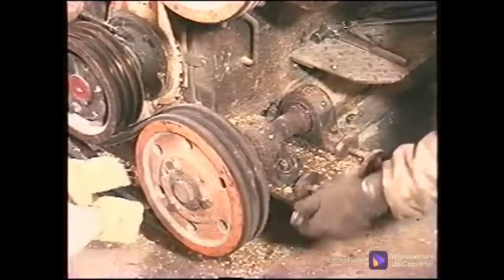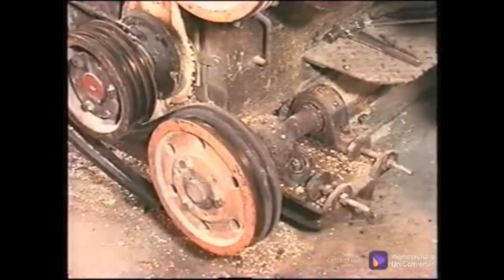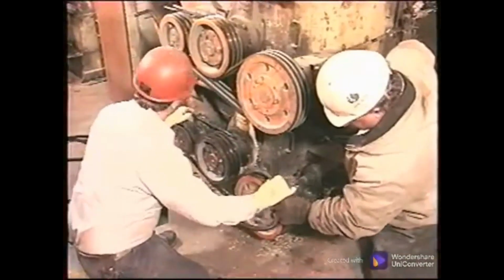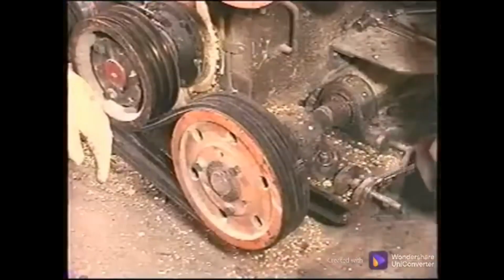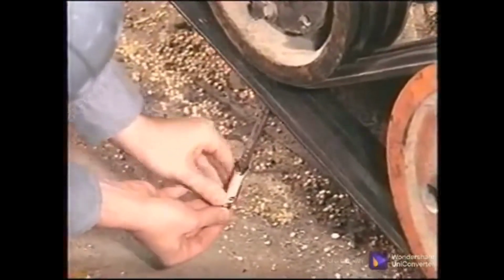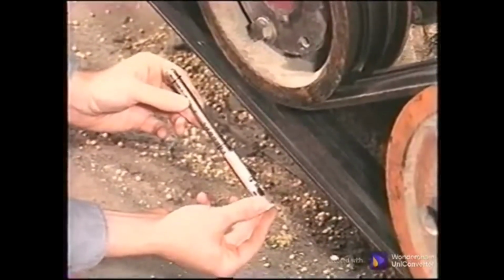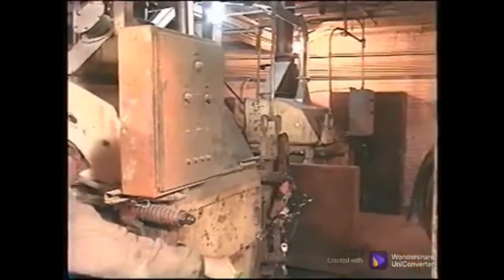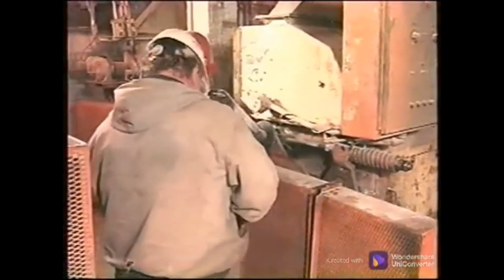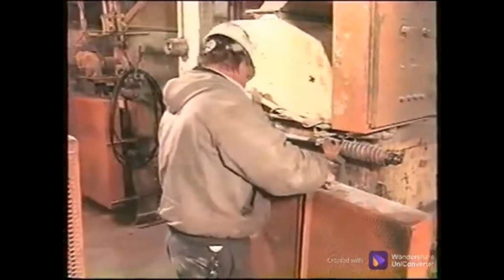Select a new matched set and remove the old belts. The tensioner is loosened enough to remove all the belts, and the new belts are placed on the sheaves without prying them into place. The tensioner is tightened and the belt tension is checked with a tension gauge. A few steps were left out of this belt replacement job due to time constraints. Some of these steps are: inspect and clean the sheaves. Check the sheave for runout, both eccentricity and wobble. And check all the sheaves for alignment.